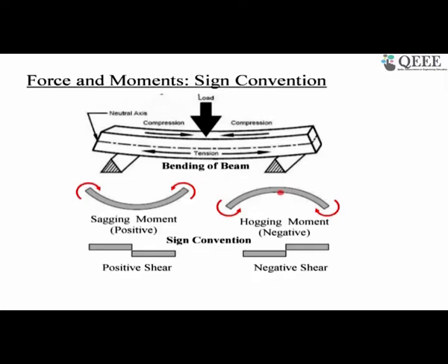Since you need to also tell the location where the reinforcement bar is to be given, and the reinforcement bar is to be given only at the tension face to take care of tension, what sign convention you use is very important. So please stick to that.